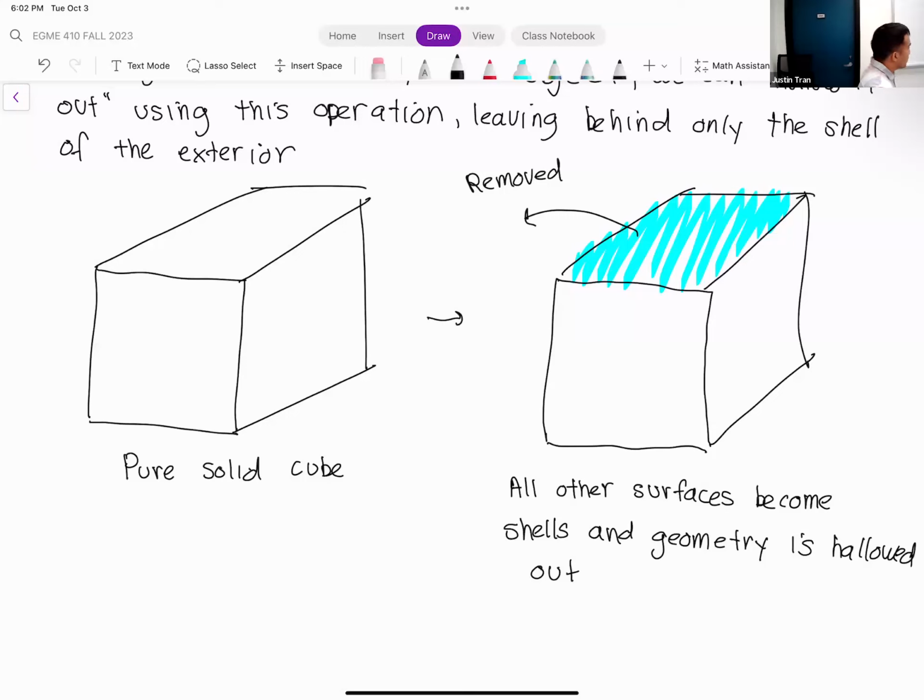And so the important thing to remember, whenever you're using ANSYS, is to keep an eye out for those blue question marks. Whenever you have a blue question mark, that tells you that ANSYS wants you to assign something before you move on. Okay. All right, any questions on this? Okay, all right, so that's everything with shells.